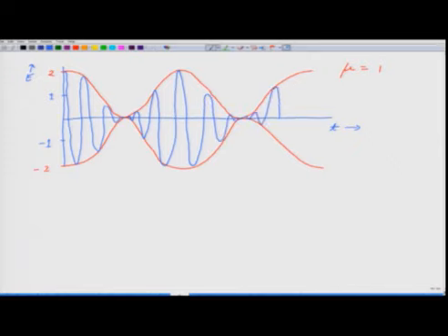And if we see the envelope of the amplitude modulated wave, it now represents the original modulating wave very nicely. There is no information that is lost if mu is equal to 1. So the maximum value of the amplitude modulation index can be equal to 1 for an efficient amplitude modulated transfer.